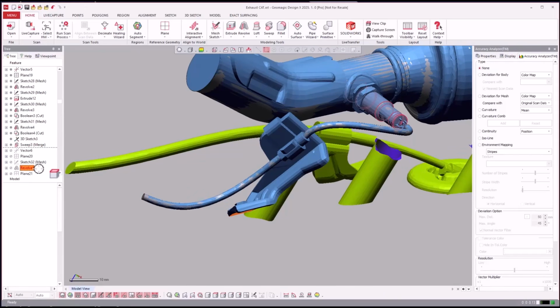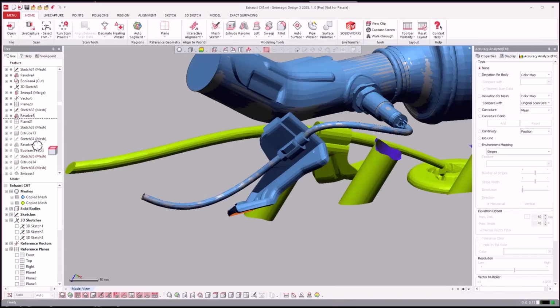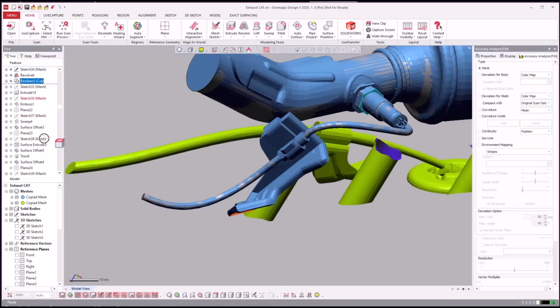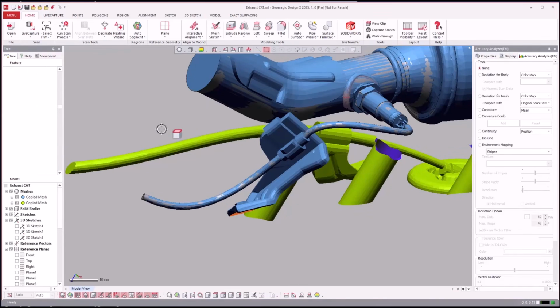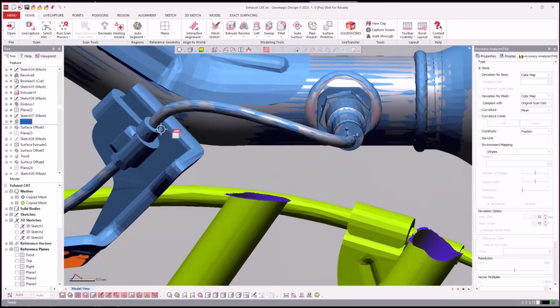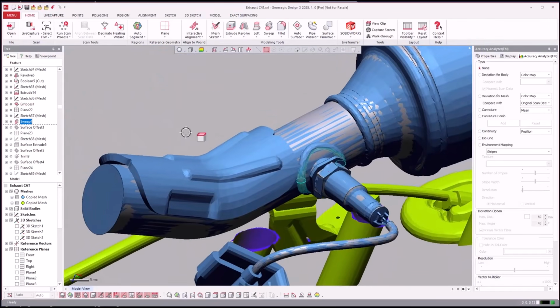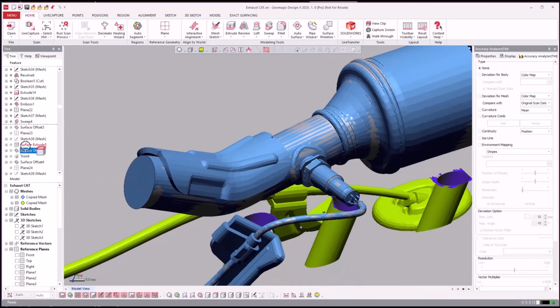And now we'll just jump forward here. Just did the revolve for the O2 sensor. Just your basic cleanup stuff for that. Modeling the hex for it too. And let's see what this next sweep is, because that's another major thing. Oh, they swept the bead around the outside, which I believe is a welded bead where they welded that adapter, so this O2 sensor can screw in. So let's jump forward a few different steps here and see what we've got.